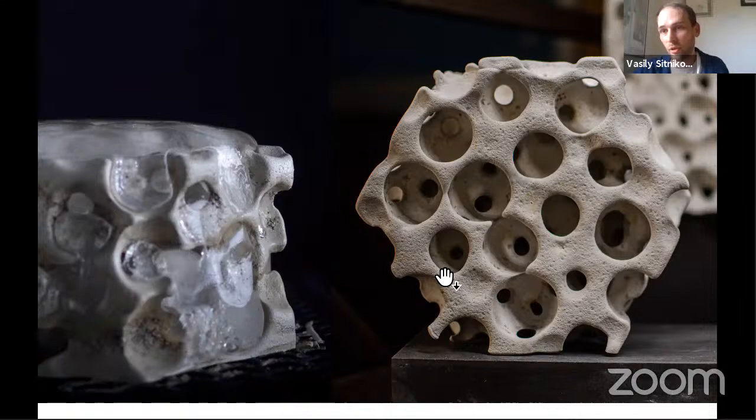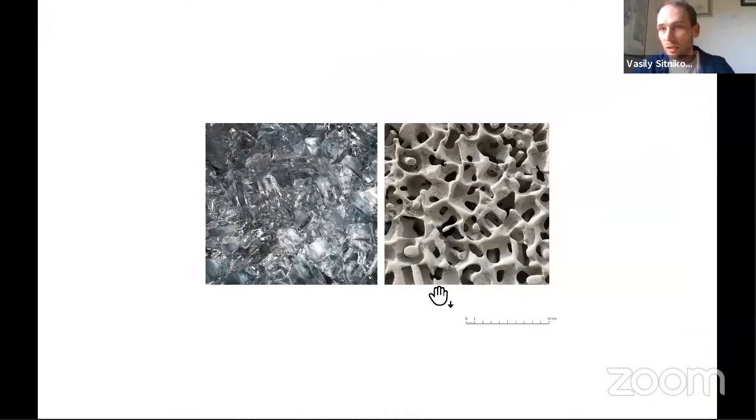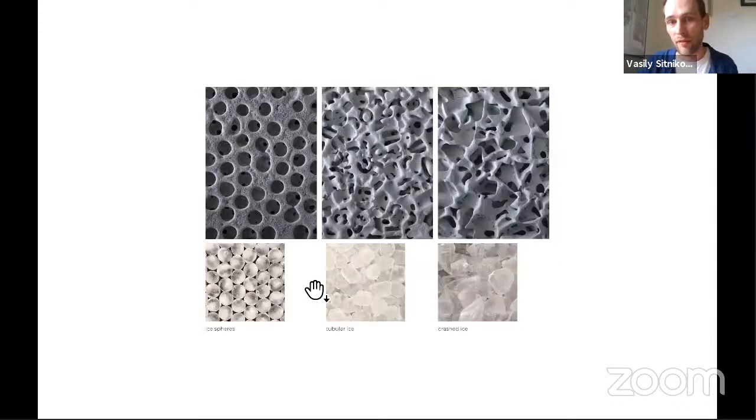Another completely analog approach is basically the use of fused ice aggregate, which also benefits from the fact that ice can melt and drain away from the formwork completely autonomously from the concrete, releasing the concrete cast. And here, depending on the topology of the ice aggregates, one can control the continuous concrete structure you can make with it. So having different kinds of ice bits, one can pretty much program what is being produced with the continuous concrete spatial structure made with it, right?